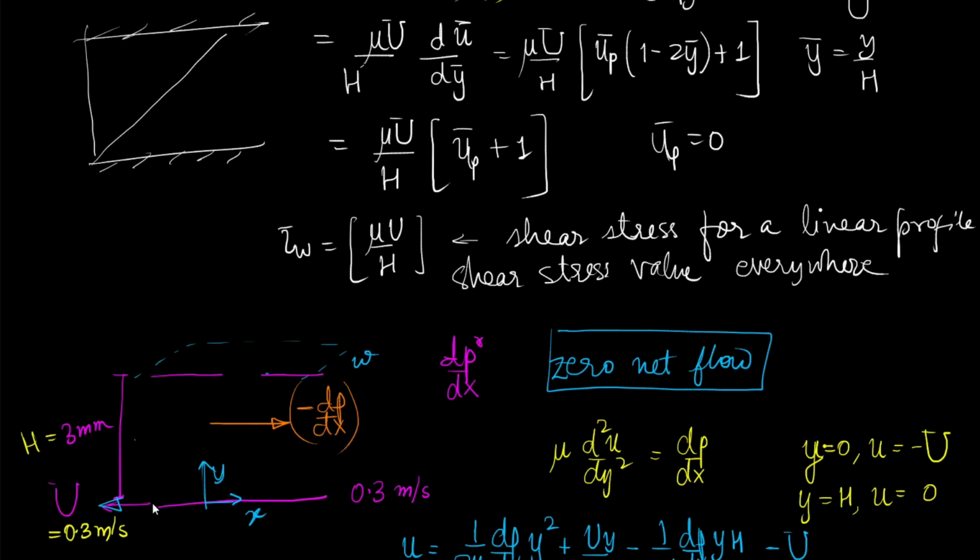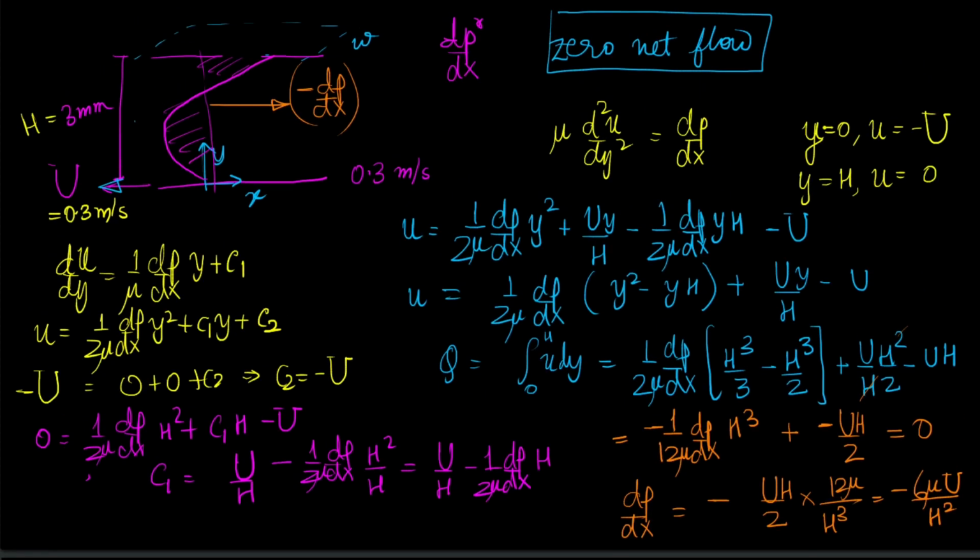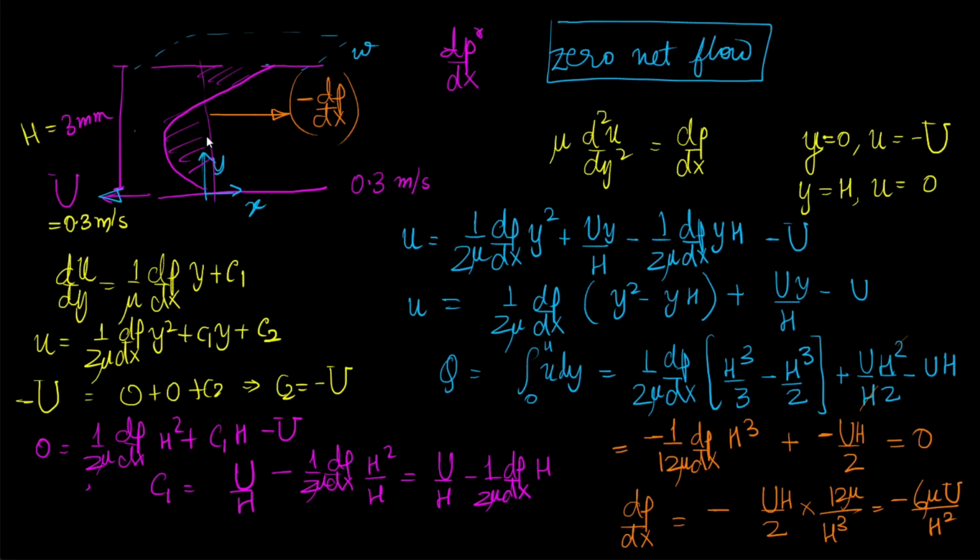The plate being pulled tries to have a velocity profile in this direction, but the pressure gradient tries to have a velocity in this direction. So it would be something like this. The volume in the negative direction and the volume in the positive direction would be balanced. Having said this, if you have a situation like this, there is no guarantee that the flow will remain stable.